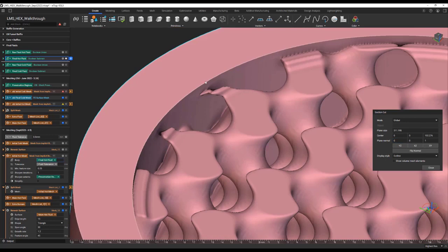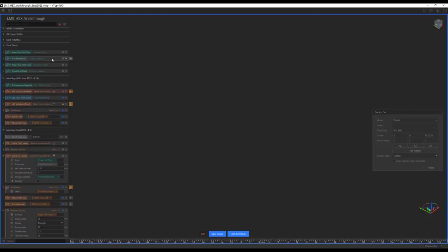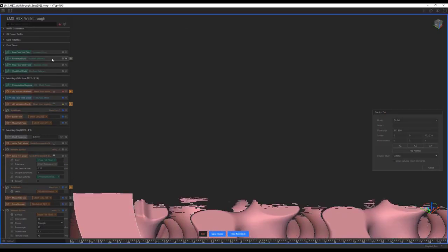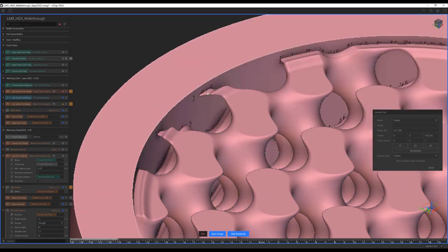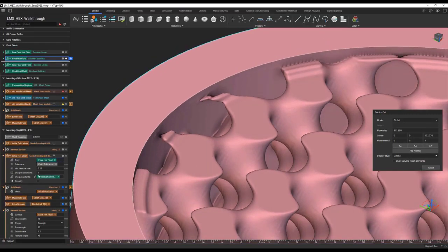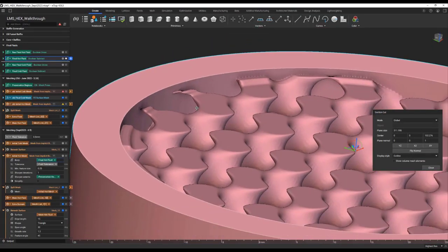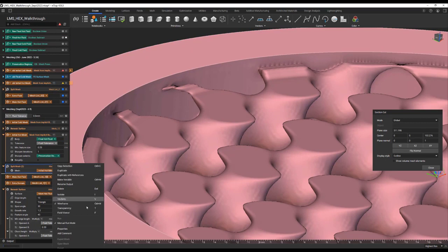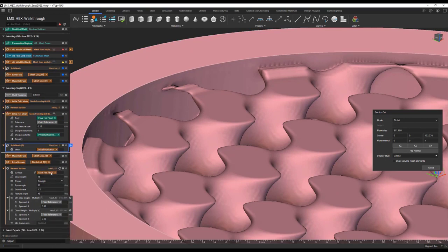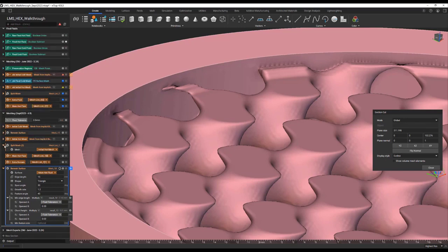But yeah, indeed here, if we do a high res render, so click the object, Control H, we'll see that we also have some pretty thin sections that were likely getting meshed and causing issues here as well. So by putting in this min feature size, we're basically telling the block to ignore anything below 0.025 millimeters of thickness in this case. We'll click play again on the split mesh here, remove the manual run mode, and while this is getting set up and running, I will set up the mesh for the solid domain and then talk you through that once it's completed.